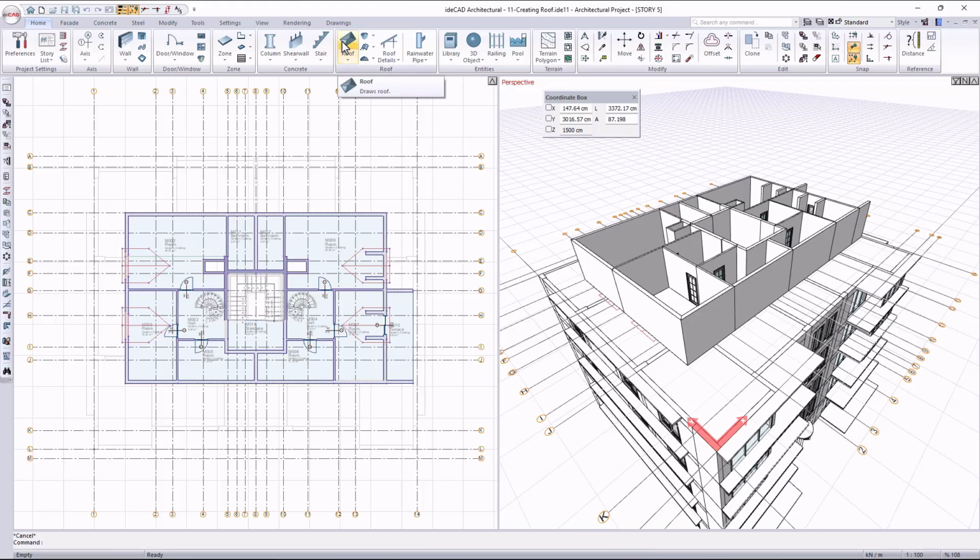The roof command automatically generates a hipped roof based on the defined outer boundaries. The roof plane command allows each roof surface to be defined individually. This enables different slopes to be assigned to each surface, offering greater flexibility and precise control over the roof geometry. The type of roof and the method used should be selected based on the specific requirements of the project.